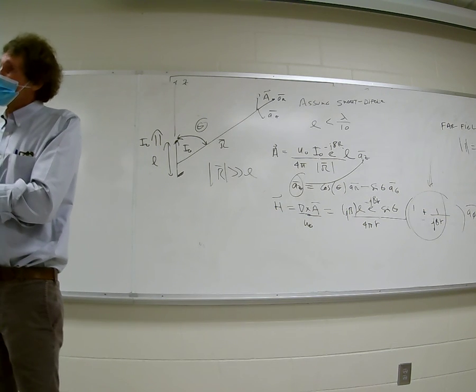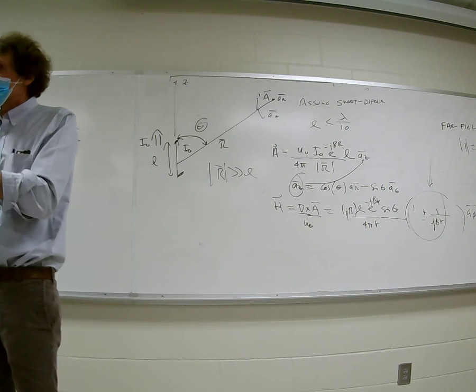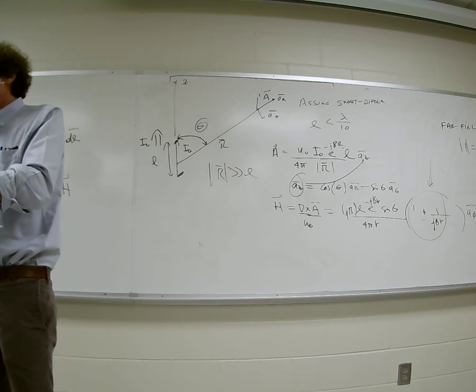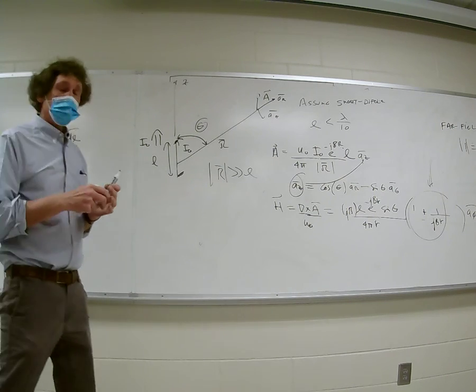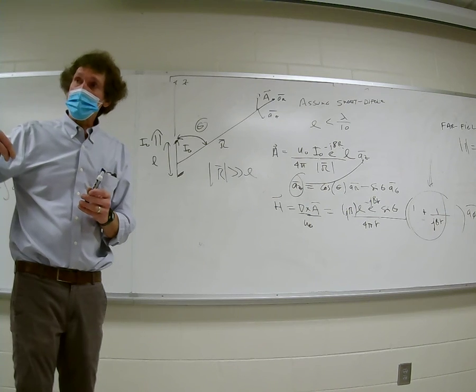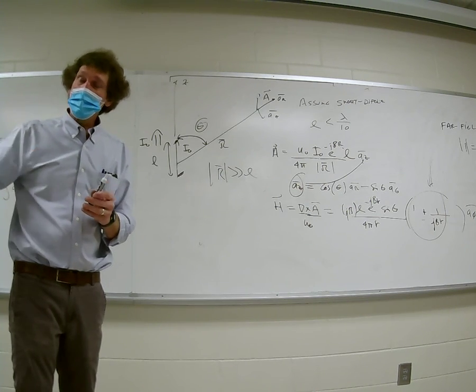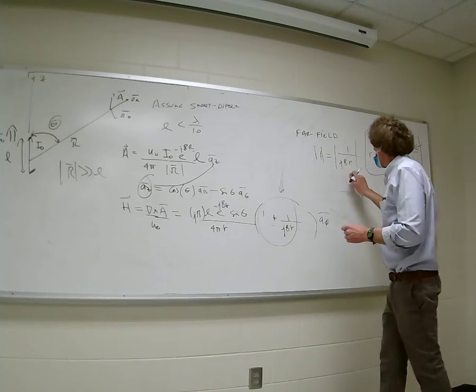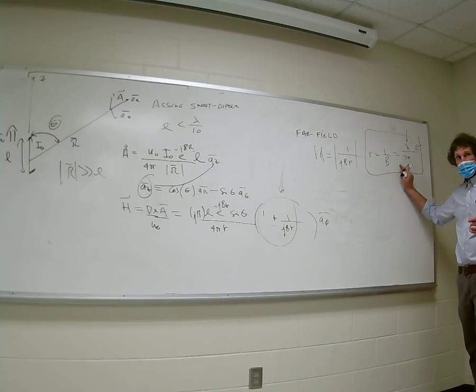There's a way we deal with this, called near field impedance. That's a more advanced topic; if I can get to it, I will. But for now, just realize, you know how you have a characteristic impedance in free space? There's a near field impedance that you have to work with, and that's a little advanced. We're not ready for that. So the bottom line is, this is the transition to the far field, right here. That's where it comes from.